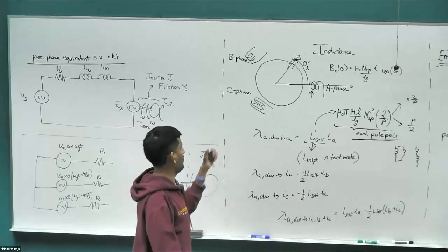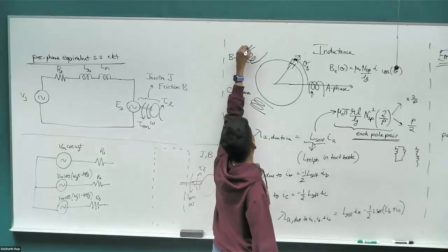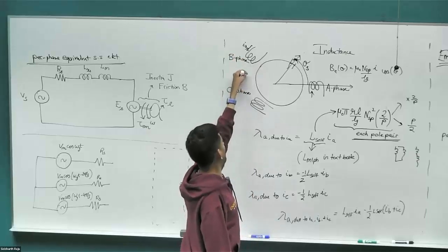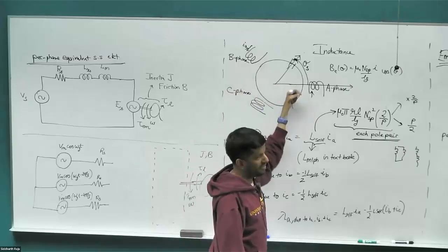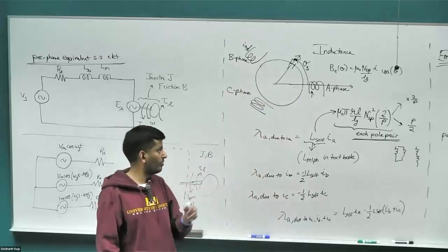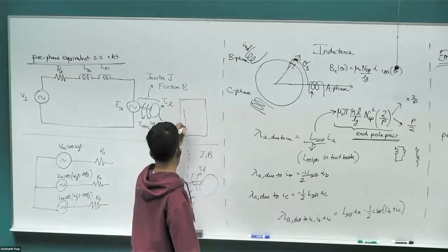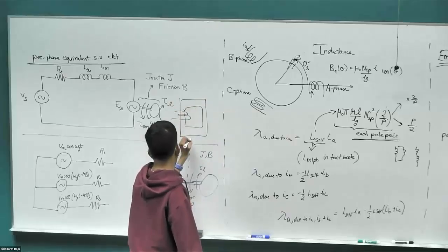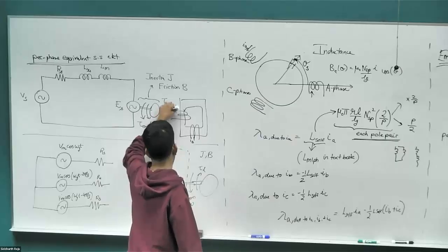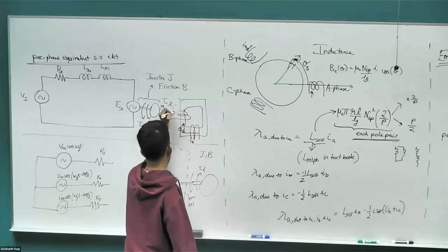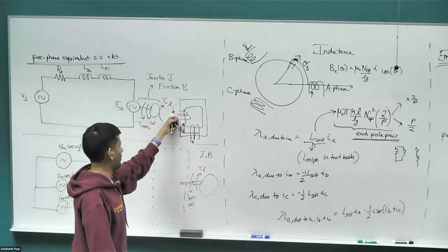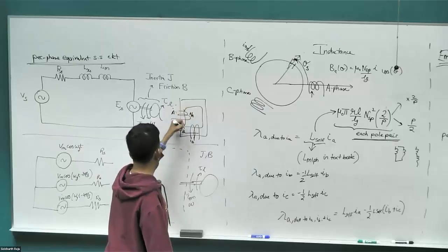And then what we saw is if we start to pass current in the B phase, then there is going to be some flux, the B field set up by the current in the B phase, which is then going to link again with the A phase coil because these are all wound on the same core. So we looked at the example we had in our midterm where we had a core like this and a second core like this. So if this is carrying some current IA, this is carrying some current IB. If, let's say, this is initially 0, if this is creating some flux phi B, this flux will link into the A phase coil to produce some flux linkage, whatever the turns are, Na times phi B.